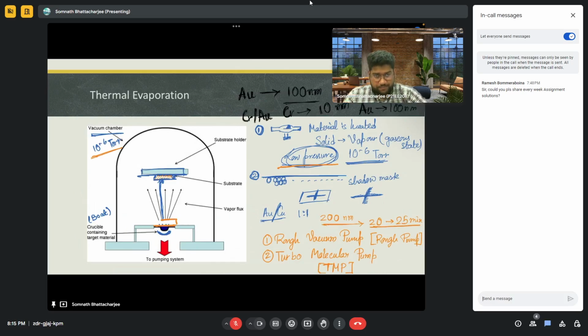So I have a question: if the required material on top of my substrate is 100 nanometers of contact, what do you think? We'll make the chrome 10 nanometers. If we make the chrome 10 nanometers, will we deposit the gold at 100 nanometers or 90 nanometers? The first question is this. Then I have a follow up question as well.